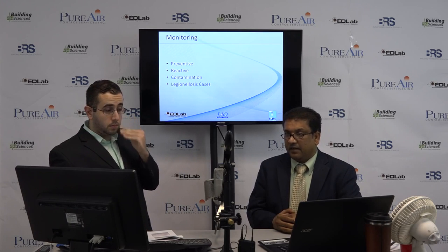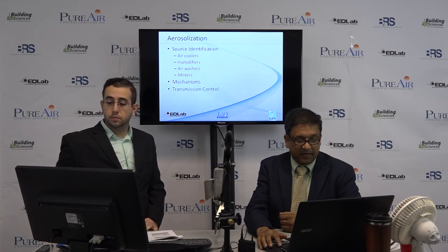In a reactive approach, you can also derive some information from ASHRAE 188 on how to address them. Contamination control is also initiated based on that information, and with the Legionnaires' cases from the local health department, in collaboration with them, you can understand what is more important in order to prevent those diseases in that particular area.